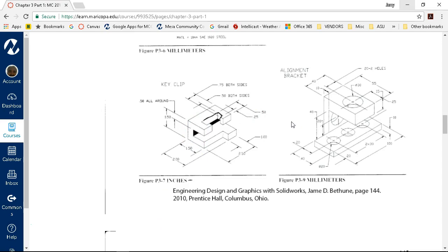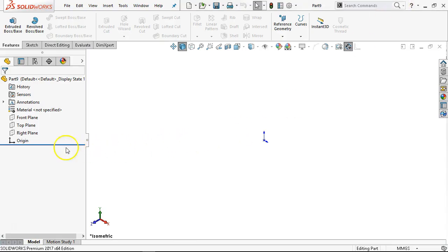So we can sketch this. You know, kind of on first look is to sketch the bottom and bring it up. But then in that same vein of what I just did with this notch, if I went with the offset and then another rectangle on the bottom, I could utilize those contours and regions to have a shared sketch. I think my first instinct on the strategy, though, is to draw the rectangle on the bottom, extrude it up on the right plane, find this geometry, and extrude it out. So I'm having too much fun with the contours and regions, so I'm going to go back to that first instinct.